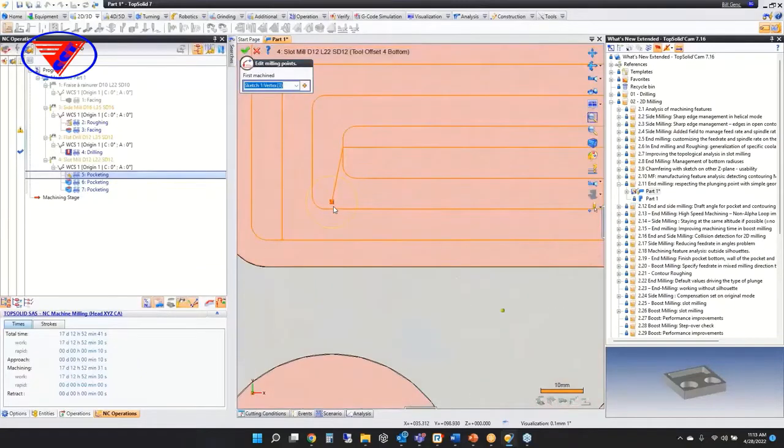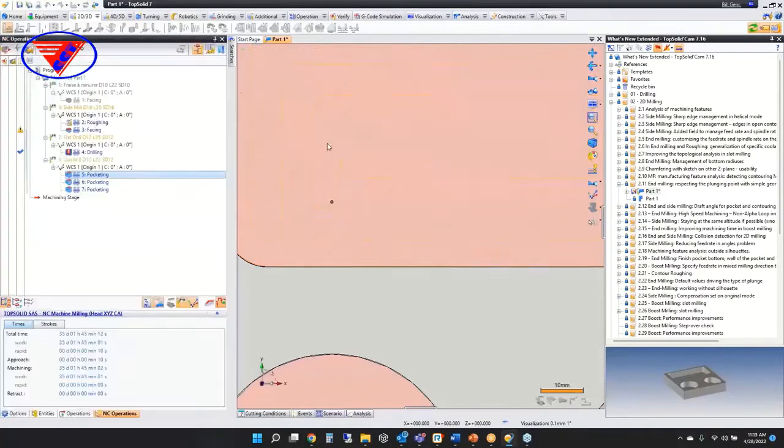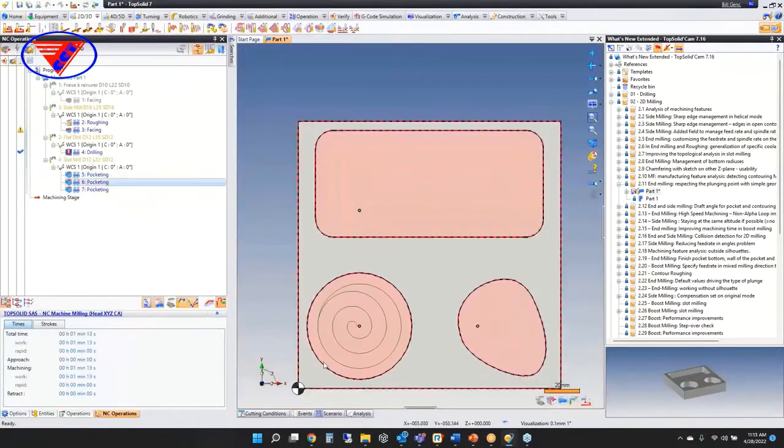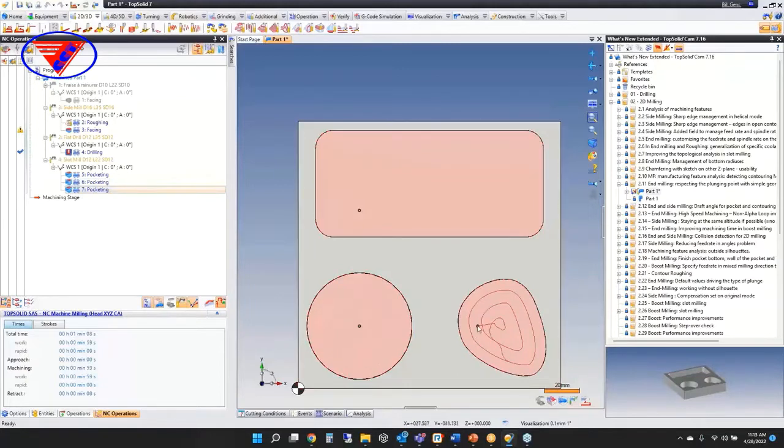And what you'll see is that it plunges there, and then it will walk over to the beginning of the toolpath, and off you go. And again, if I show you this in that one, you can see it's doing this because simple geometry optimization is for circular or square type of shapes. And of course here, same concept. It's respecting the plunge point even though it's nowhere near where it's starting. So you can get it to do what you need it to do.